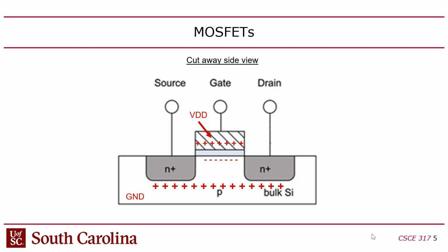It depends on the electricity flowing through here, right? The problem is that if you ask too much of this transistor, if you ask it to source a lot of current, it saturates. And it does that because according to Ohm's law, if you want more current, you got to drop more voltage between the drain and the source. If you drop more voltage, then the average voltage starts to drop, because there's a bigger voltage difference between these two sides of the transistor. It starts to be harder to get the gate up above the average voltage of the channel, because the channel has got this huge amount of current flowing through it, and so the voltage gradient is changing wildly, right? So what ends up happening is if you ask too much, it pinches it off and it saturates, right?